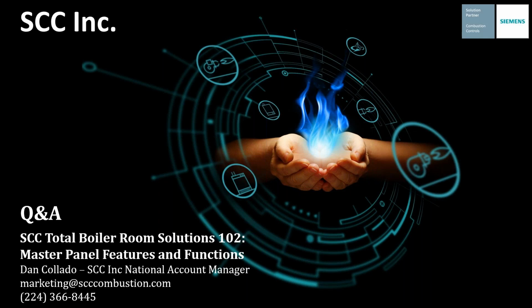You could use the SCC Inc. DA surge tank panel to do that, and then using an Ethernet connection between that panel and the master panel, you'd be able to view and monitor all the information on that DA panel and then communicate it back to the BAS. Good question.